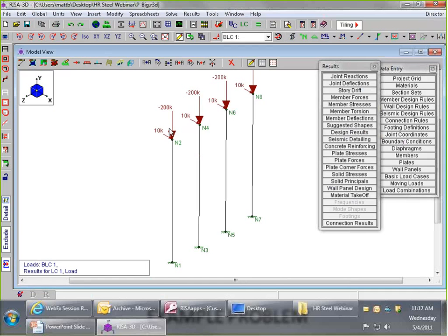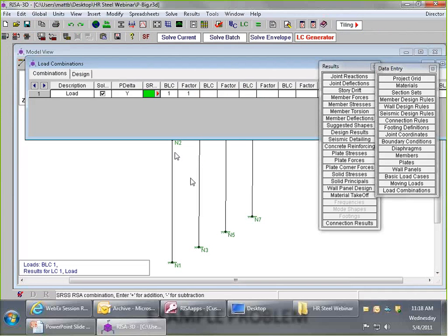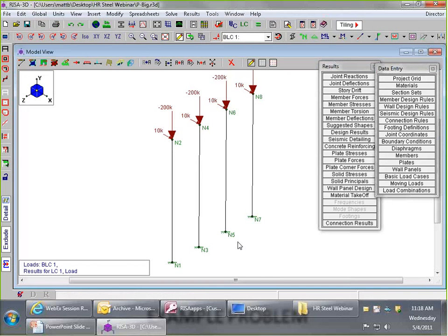Now, we do this by a method called virtual shears, and it's basically a shortcut method in finite element analysis that allows us to place imaginary additional shears on this column in order to reach the final deflected shape. And that is different from a true nonlinear solver, which we don't have. A nonlinear solver would cause the program to slow down considerably, as it would have to rebuild stiffness matrices for each one of these columns each time we created a copy. So now you can see how P-Delta works in that regard.